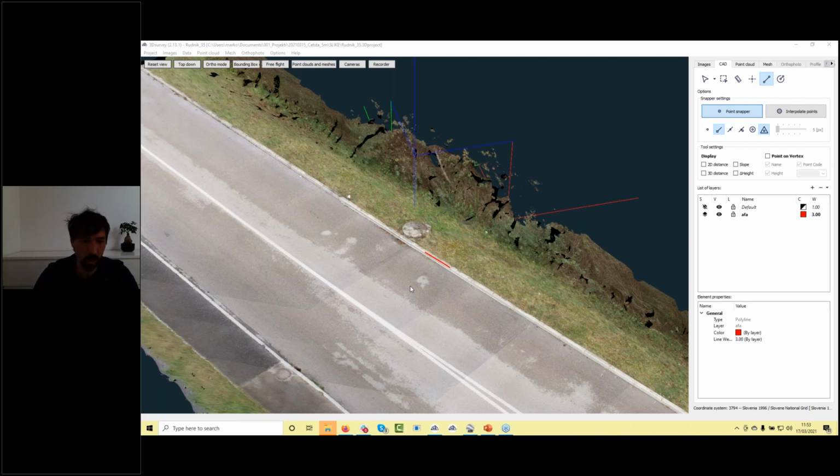Okay, so I'm using a Phantom 3 Pro with GPS, with GCPs, also good enough to do this type of work? So the Phantom 3 Pro has different cameras, so it's not so powerful. It's rolling shutter camera. Of course, it also works, so you could get similar results, but definitely place more ground control points on your area. At least 10